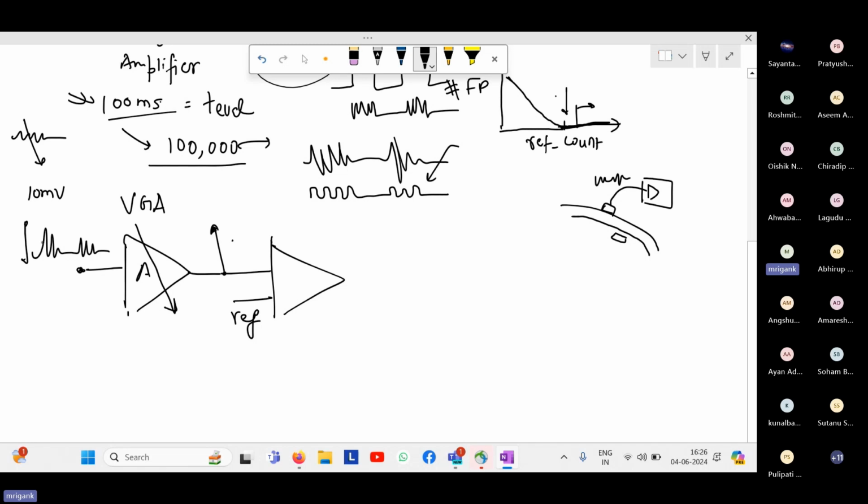So if somebody tells you that this sensor will give you the maximum peak to peak seizure signals that will come, it will give you something from 1 millivolt all the way to 100 millivolt. That means, or say 10 millivolt to 100 millivolt. So in certain cases, the seizure signal may be just 10 millivolt. In certain other cases, it may be as high as 100 millivolt. Or I can go for more extreme values. In certain cases, suppose the seizure signal is only 1 millivolt. So depending upon that, I will have to tune the range of the gain.